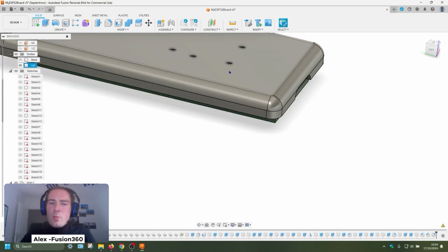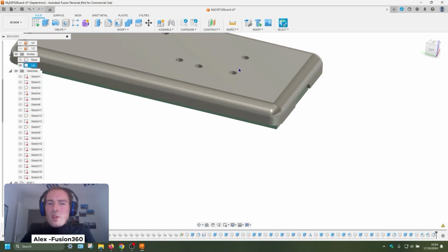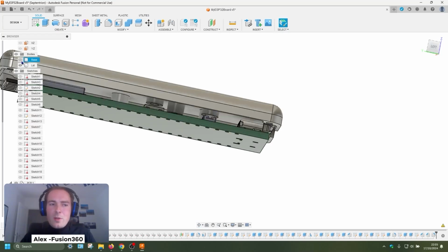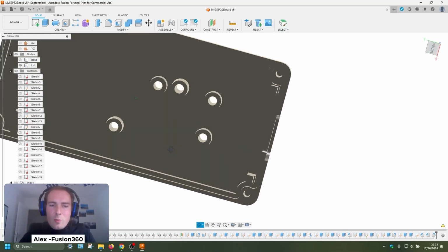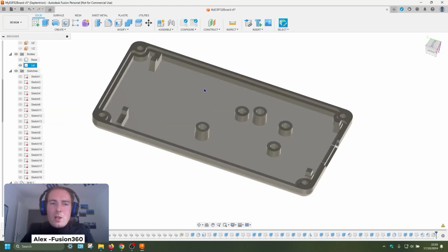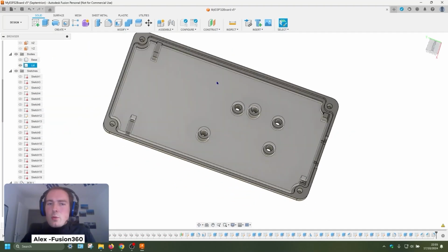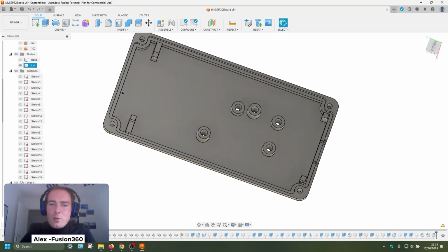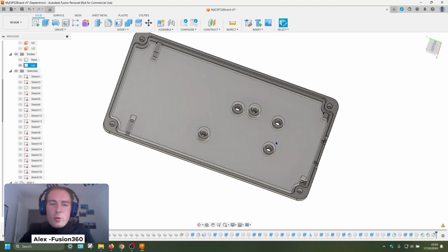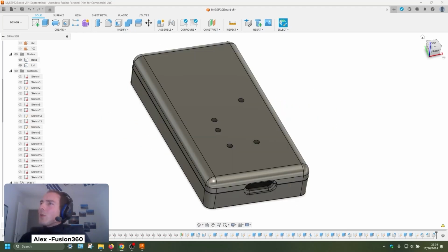You see for all of the buttons I just made holes, so presumably you're pressing them with a pencil or something. And I did surround them properly, as you said, to avoid light leakage and heat leakage from your lead and everything. But apart from that, it's a really basic and functional design. I did do an injection check right now, and it's 100% perfect for quick injection molding. What I could definitely have done here if I had the time was, instead of having buttons, have shaped cutouts so that the plastic flexes a bit when you're pressing on it, and that acts like a button. Then you're not making extra molds. That would be the minimal price solution right there.